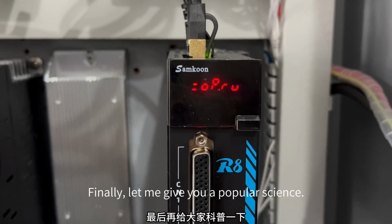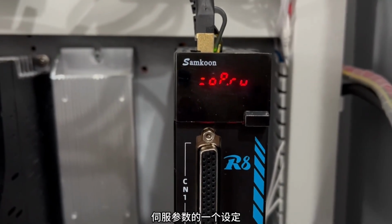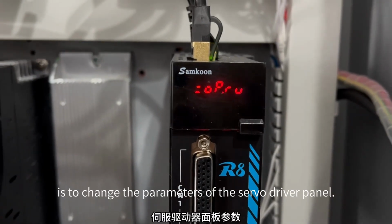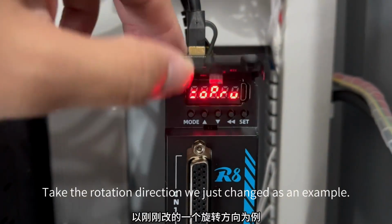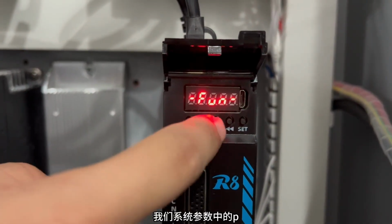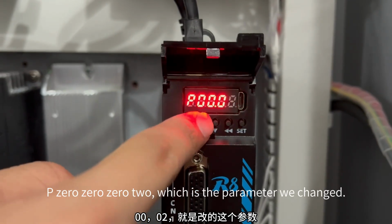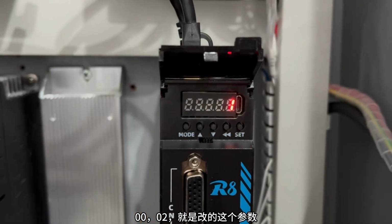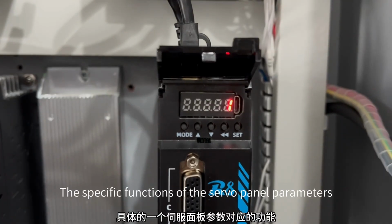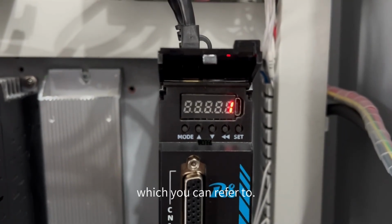Finally, let me give you a popular science. In fact, the servo parameters setting of the system is to change the parameters of the servo driver panel. Take the rotation direction we just changed as an example. It is actually changing the parameter P0002, which is the parameter we changed. The specific functions of the servo panel parameters, we will have a detailed manual, which you can refer to.